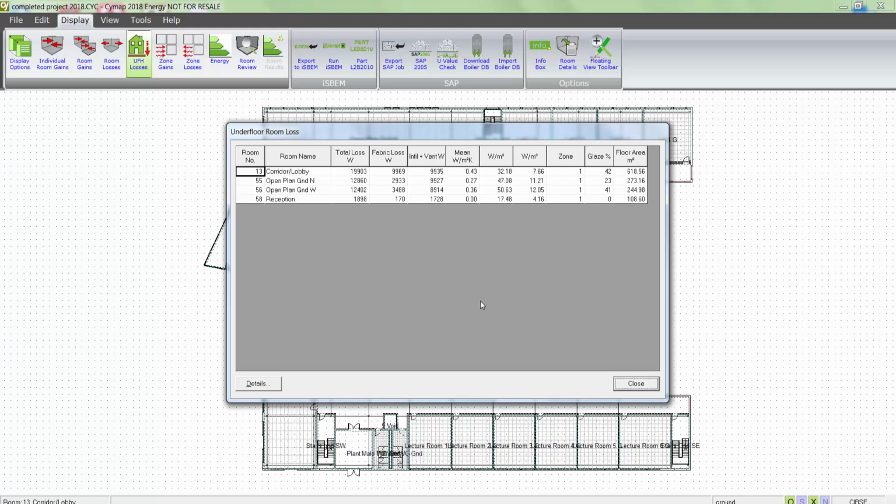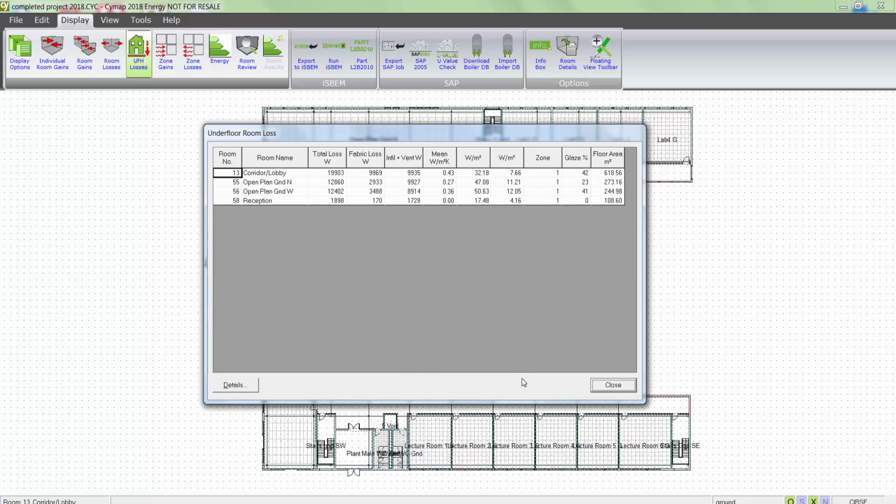Underfloor heat losses can also be undertaken to allow the engineer to look at the viability of whether to use the underfloor heating as the prime heat source or as a secondary heat source based on the provision of heated fresh air to the space. This can then be supplied to the contractor to enable the engineer to size the pipework to the manifolds to the space.